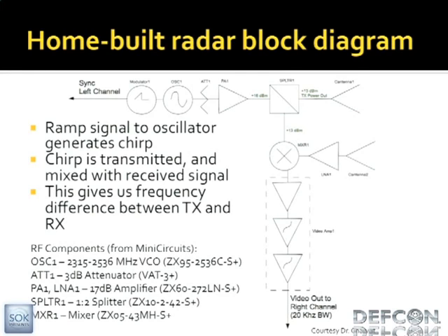So you send it a ramp, and it gets faster and faster, and that generates the chirp I was talking about earlier. There's an attenuator, power amplifier, which just makes the signal louder or more powerful. That signal gets split, and one of the copies gets transmitted out by one of these dishes here, coffee cans. Sorry. The other part of the signal goes to that mixer,